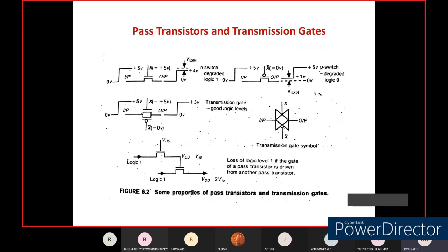So what we use is an intermediary called a transistor to couple or combine two nodes in a subsystem. Once again, this pass transistor is used to couple two terminals or two nodes within the subsystem, and the voltage degradation in this subsystem will be VT.